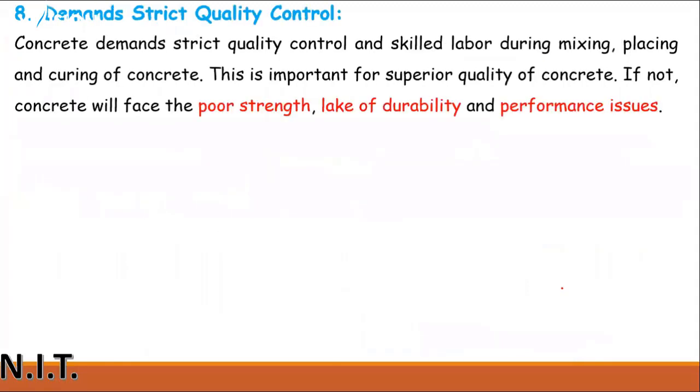And the last limitation is that it demands strict quality control. Concrete demands strict quality control and skilled labor during mixing. If your mixing quality is not good, you cannot achieve high strength concrete.